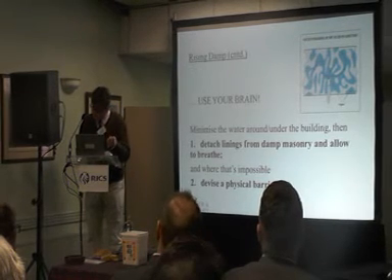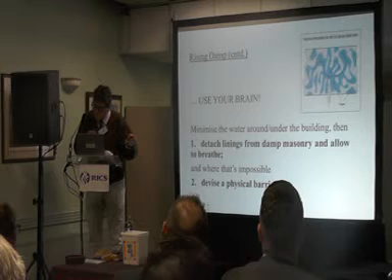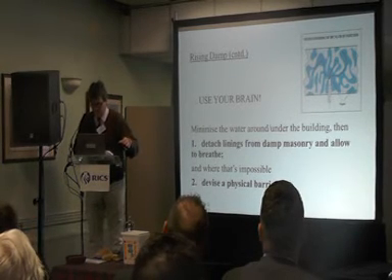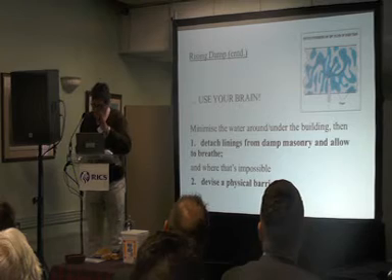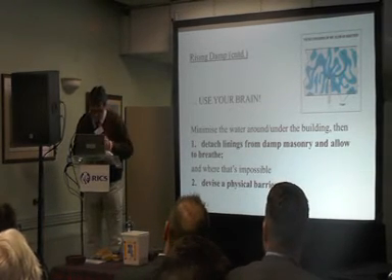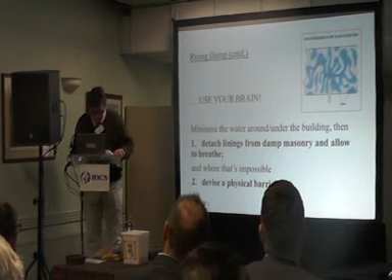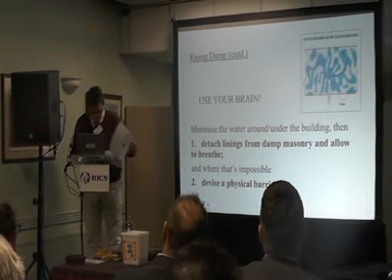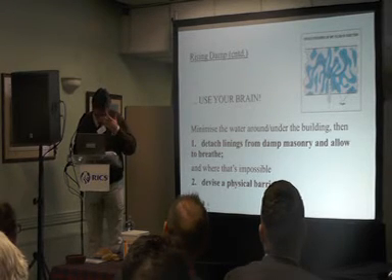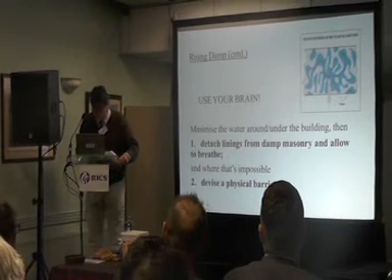You think you can drill a hole in it and stick some silicone in the hole, and somehow all that water is going to get displaced and replaced with silicone and make a damp-proof course? Oh, come on. What planet are you from? This is the biggest con in the whole world of damp-proofing and building repair. The electro-osmosis is certainly not proven, and the little weep holes, well, they can't do any harm, can they?